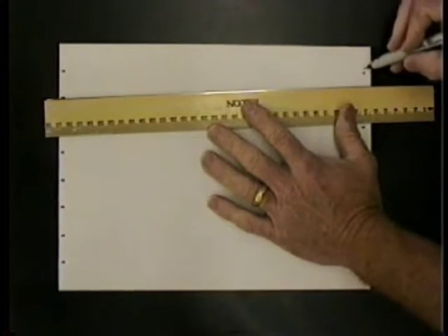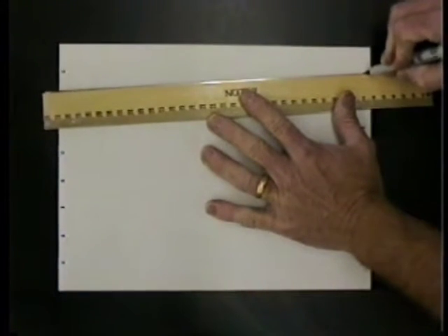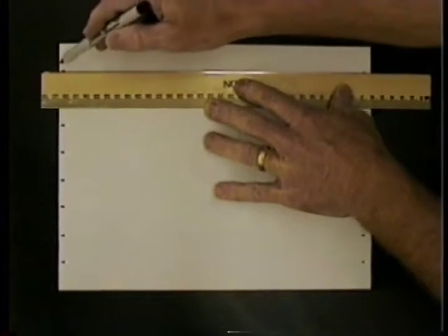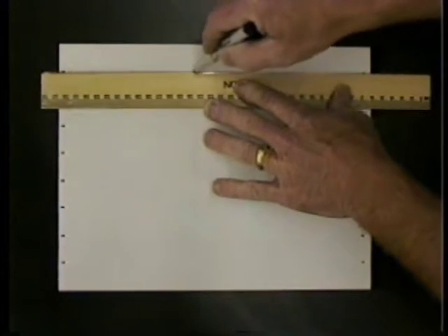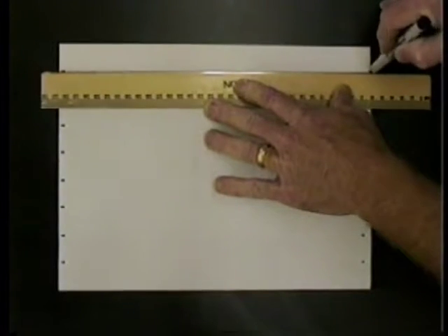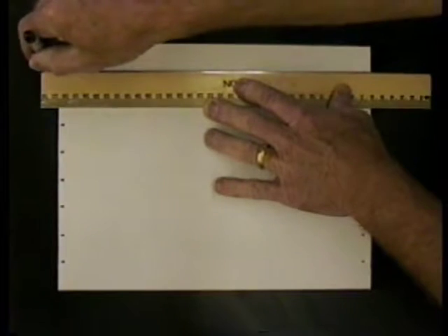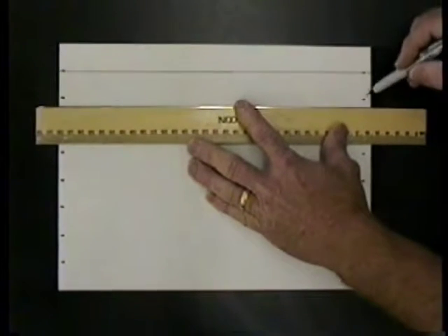When both the top and bottom have been marked, draw lines from the top to the bottom edges of the paper, connecting the marks. An easy way to do this is to place the pencil point on the bottom mark. Slide the ruler up to it. While keeping the bottom pressed against the ruler, line it up with the top mark. Press down with the thumb and fingers spread and draw the line from the top to the bottom, keeping the pencil pressed against the ruler.